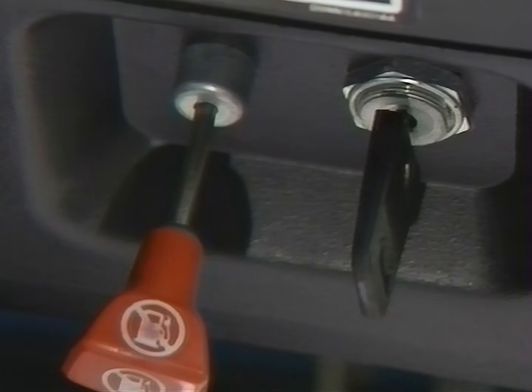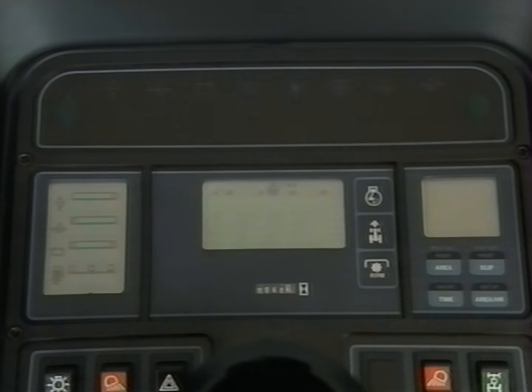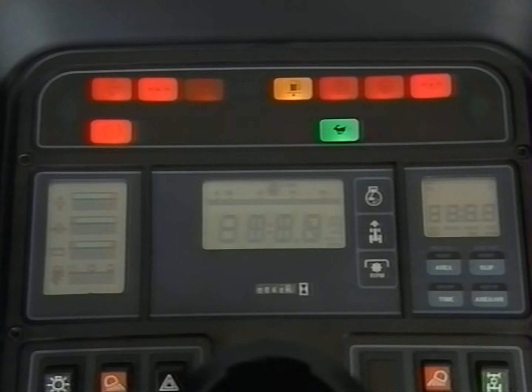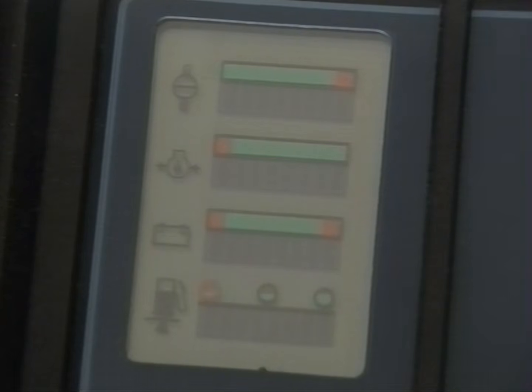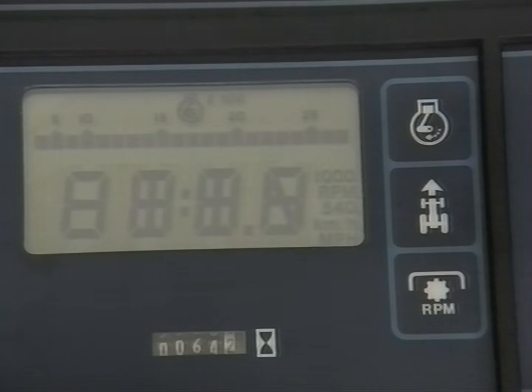Under normal operating conditions, when the key is first turned to the on position, the warning lights that are not ordinarily lit light for 2 seconds to show that their bulbs are working. The 4 bar graphs display all segments for 2 seconds before displaying actual conditions. The rocker switches indicate whether the hazard warning lamps are on or the front wheel assist is engaged. And the digital display runs its various types of readouts for 2 seconds as a self-check. It's then ready to display engine RPM.